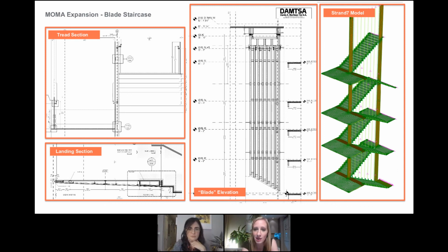Do you think that a landing can be considered to have a different, narrower frequency range compared to steps, using a walking frequency range similar to that of the floor? People are not really ascending or descending, but rather walking on a flat surface, one might say. Agreed. Yeah. On stairs, particularly with switchback landings like this, the frequencies you're considering on the landing itself would be closer to walking rather than ascending or descending stairs.